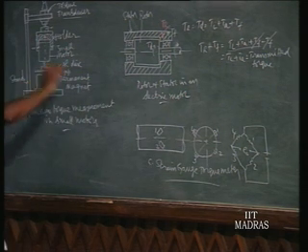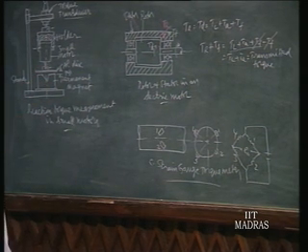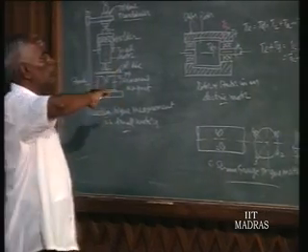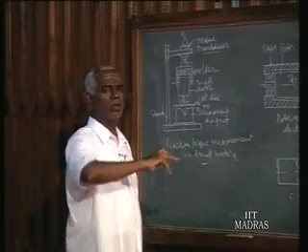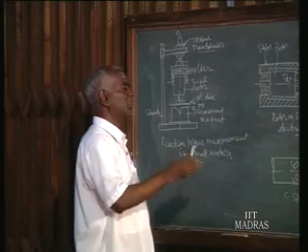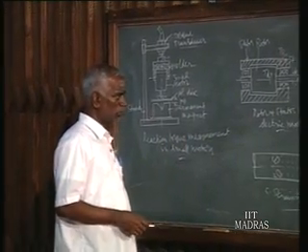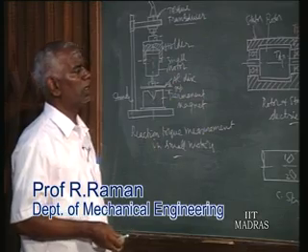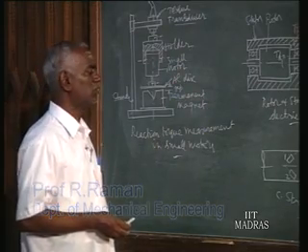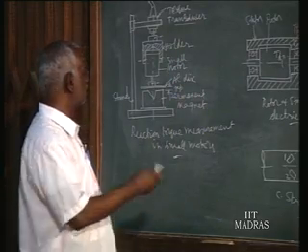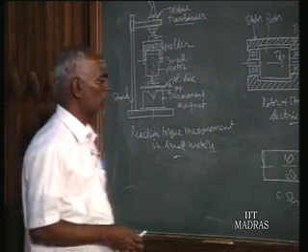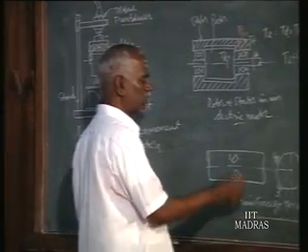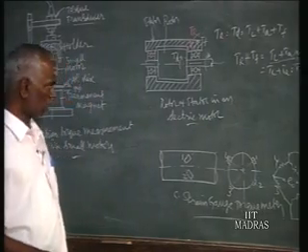Bigger motors you have to mount in trunnion bearings, but the friction torque in the trunnion bearings is the error torque, the error in such reaction measurement. So when you select bearings for the trunnions, they should have a very low coefficient of friction. Such bearings we should take, and it is possible to keep the error within the limits. Now, the strain gauge torque meter is more precise and also widely used.